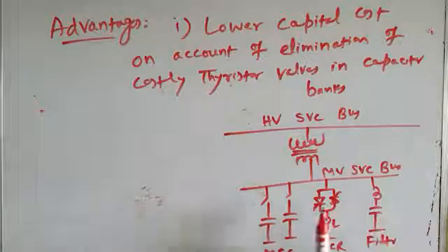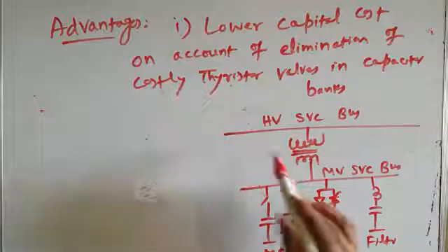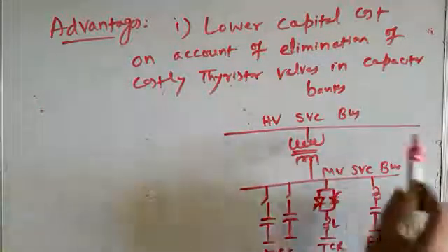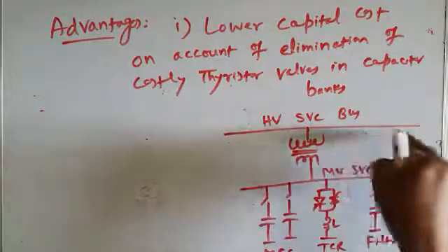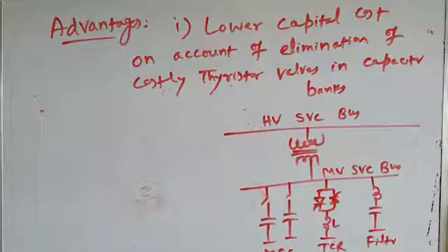And then these two balance the reactive power supply on the bus, and hence they maintain the bus voltage nearly constant. They provide bus voltage support, improve the voltage stability of the system, improve the transient stability of the system, quickly damp the electromechanical oscillations, and also increase the power transfer capability of the existing transmission line. Okay, so this is how the SVC works.